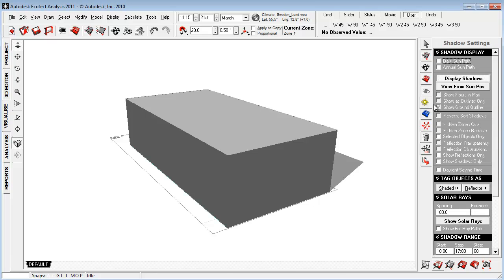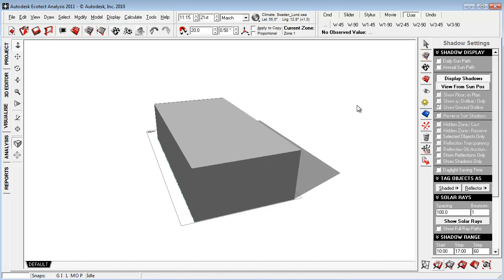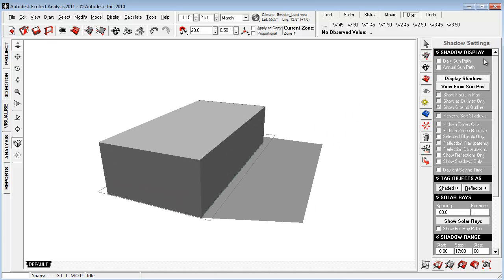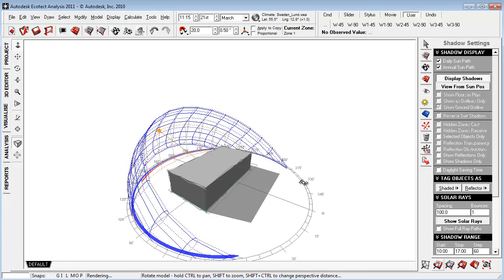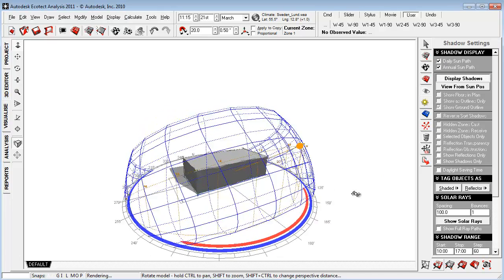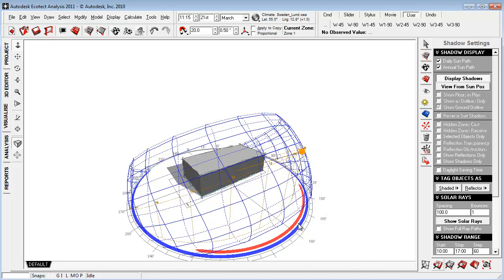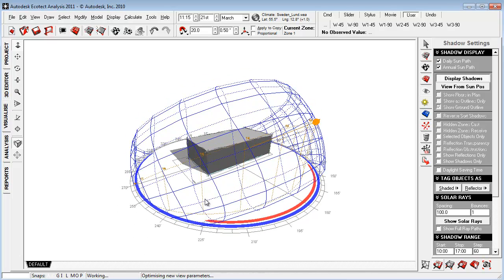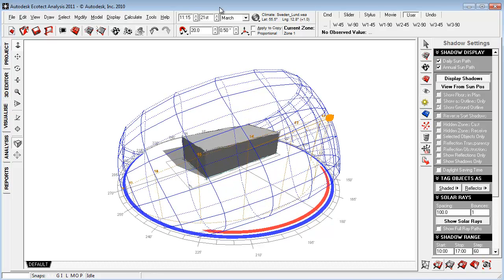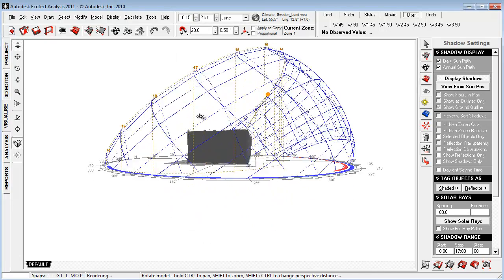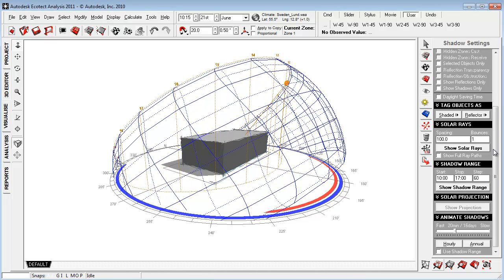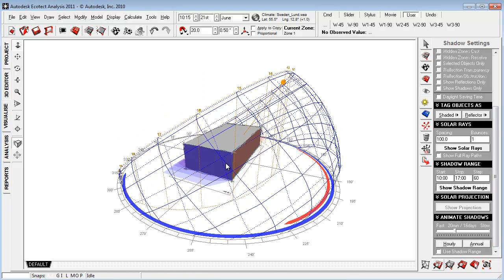So if we go to the sun settings here, you'll see that this is really a lot of times where we'll get started. So we can add on our daily and annual sun path, and from the weather file, the hottest and coldest month will be displayed inside the model, and we can then just hit here to scroll for a specific time, or we can hit the globe to go to different sun extremes or window or whatever. We are also able to hit solar rays or to make a butterfly diagram with some very nice colors and stuff like that.